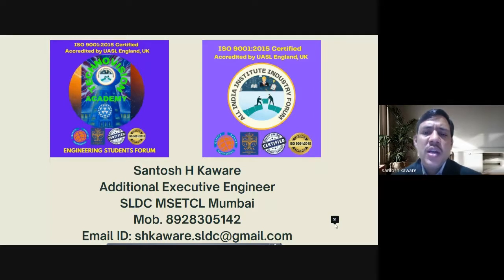So generally, at our site, we take the field test, and during energization, if we have completed the factory test and then some of the field tests, then we actually energize the system, and even there is a proper procedure we have to follow. We have to take the permission from the electrical inspector of the respective district. We have to apply to the electrical inspector.